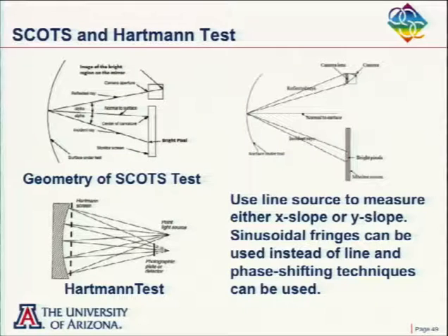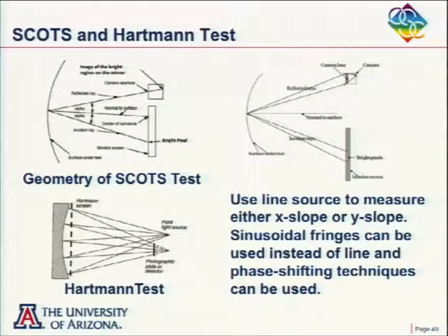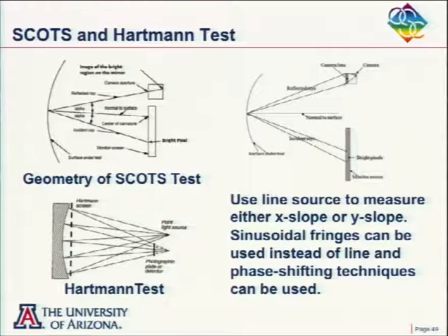I guess that's nice. You can test mirrors. Well, that's why Roger went to it originally, for testing mirrors that really do not have a great shape at the beginning. And as long as you can test it, then you can keep making the mirrors better and better. But we do have very good agreement with interferometric tests. If we have the exact metrology of the setup, then you can get very close to the interferometric test.